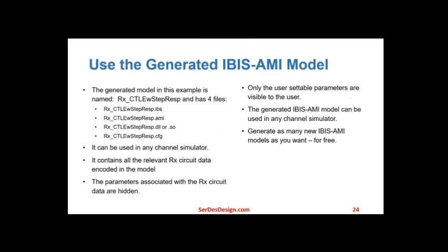The generated IBIS-AMI model can be used in any channel simulator. Only the parameters exported during IBIS-AMI model generation are used. The user can define the names for those exported parameters. Generate as many new IBIS-AMI models as you want for free.